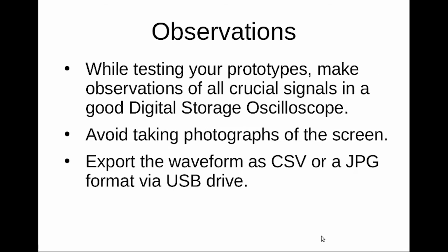While testing your prototypes, make observations of all crucial signals in a good digital storage oscilloscope, because of course DSO is the norm now. If possible, avoid taking photographs of the screen. Instead, you can use the export facility available in most of the modern oscilloscopes.